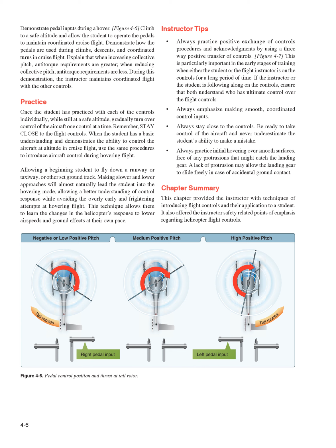Always practice initial hovering over smooth surfaces, free of any protrusions that might catch the landing gear. A lack of protrusion may allow the landing gear to slide freely in case of accidental ground contact.